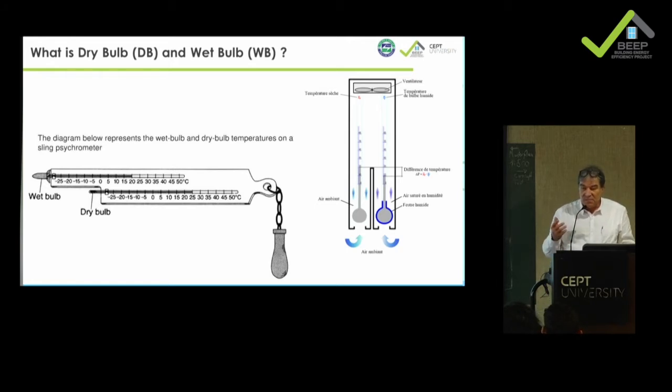The wet bulb is simply that you have a sensor. One is dry and the other is contained in a kind of wet wrapping. We call it wet bulb because of this. You have a fan which is drawing the air through these two channels. This one is dry. This is an old system which is not used much today, but is still very accurate.